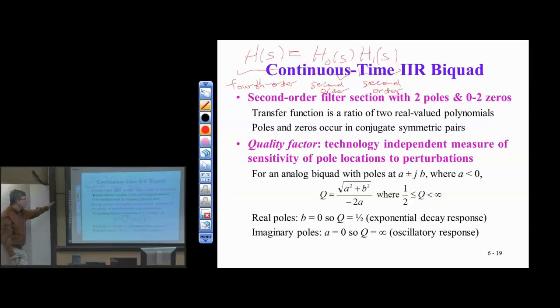So again, if I want to implement a fourth order continuous time filter, it's just a cascade of two biquads in continuous time. The order matters, and so what you can do is try both and see which one is a better filter, better magnitude response, or whatever you're looking for. Simulation, so you can do this in SPICE if it's continuous time, or in the discrete time case, we just run some test signals through and see what happens. So the discrete time case is easier. We can just simulate that on the computer, all possible combinations.